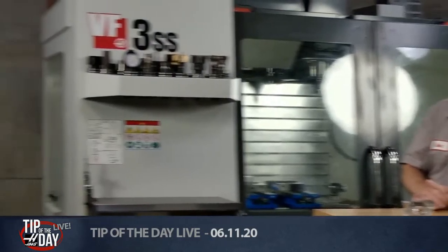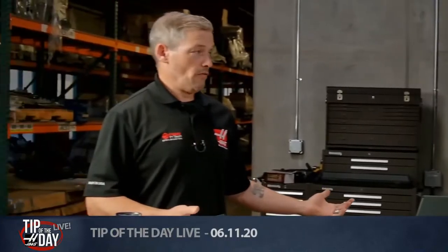So there's lots of cool things that you can do to make up for any problems you're having. But no matter what you're doing with machining, lathe or mill, the recommendations are just that. They're just recommendations, and they're usually best case scenarios. Yeah, rigidity of the machine, rigidity of the work setup, how far your tool's hanging out, all those things are going to affect that. I mean, there are endless variables, of course.